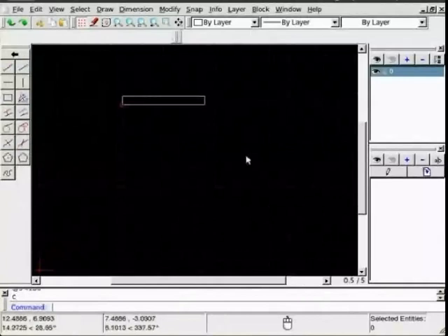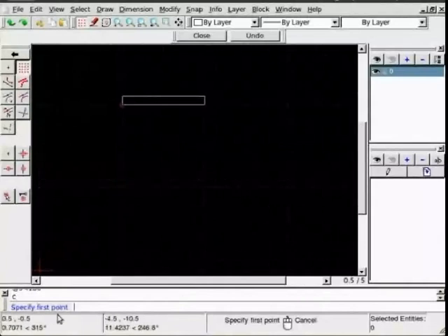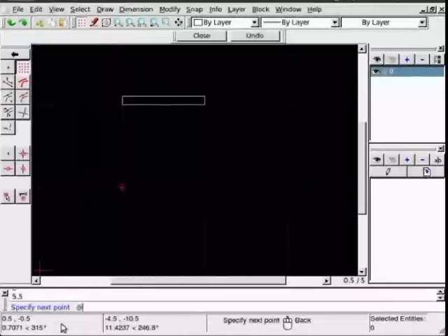Now I need to draw a trapezoidal portion which is at the 45-degree angle. I'll first draw it below this and then move it back. So draw a point slightly below the original one, so 5, 5. Next point will be at, now this side is little shorter than 5, so I'm taking 4, angle 0.